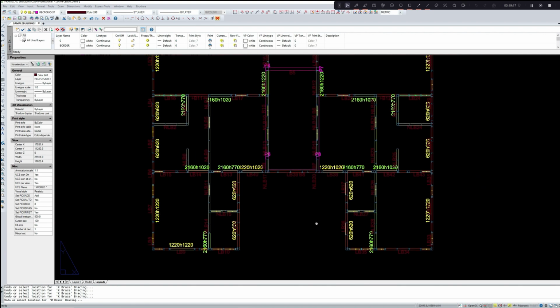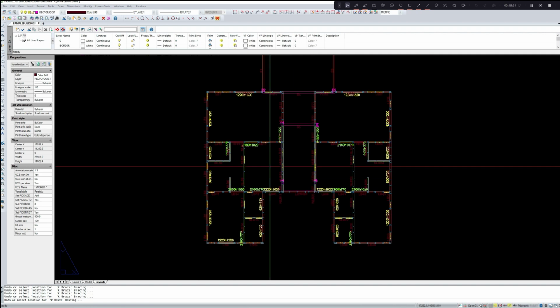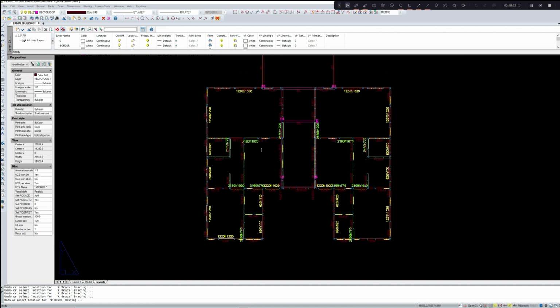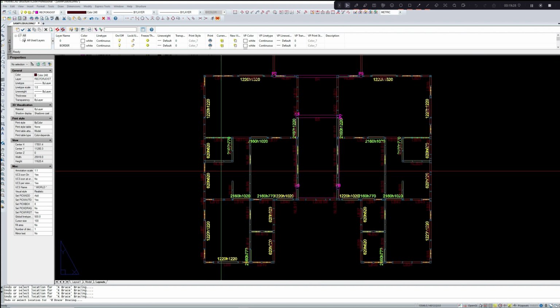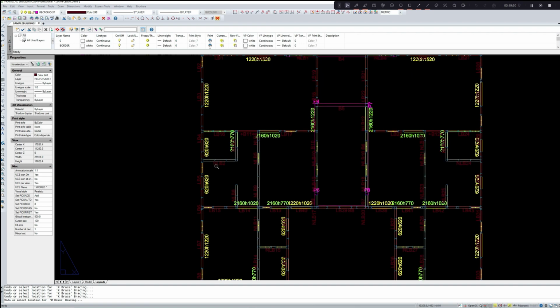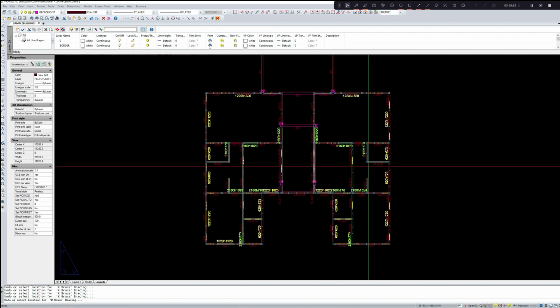So that will probably manage the resistance developed by these strap braces. Now this is almost at the middle of the building, so if I provide a strap brace here, then it will contribute similarly to both sides.